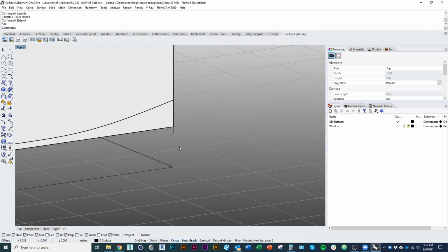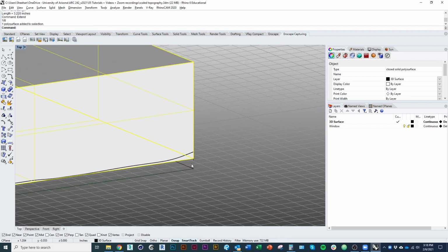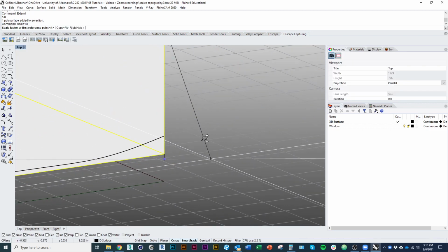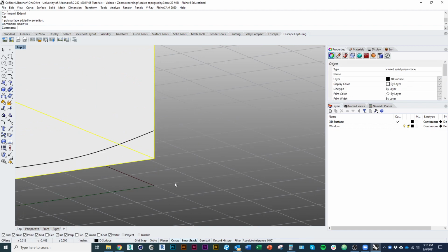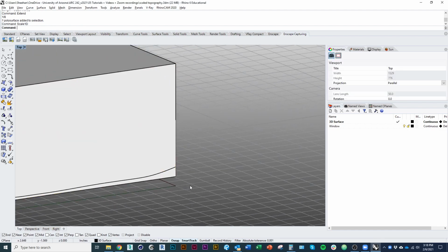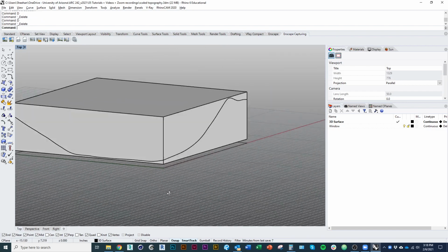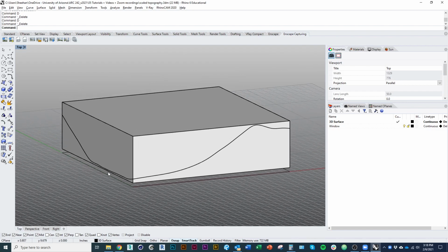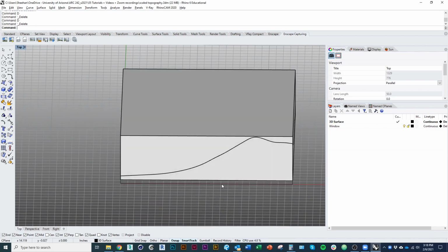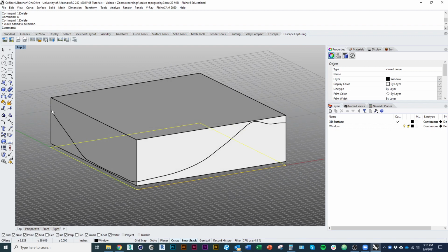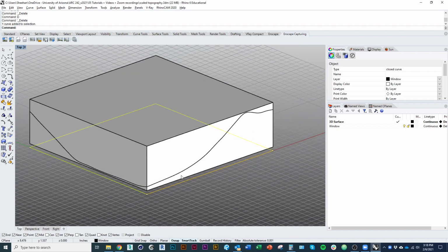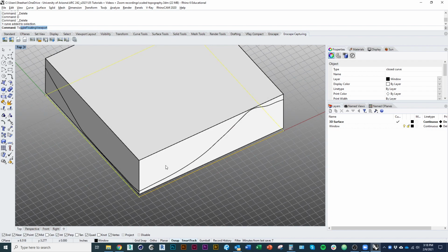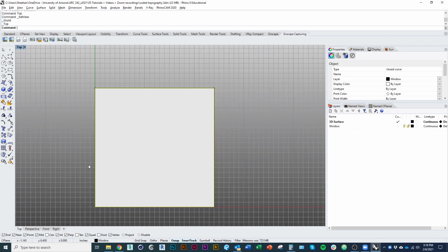And so now that line is 1/8 of an inch below, and I can scale my bounding box to that. Scale 1D, go from the midpoint of the box to the bottom, and then snap to that line I just extended. Easy enough. Okay. So now I have a box that's going all the way around my model. Again, because I used this window when I originally trimmed my topo surface, I know that that box is going to be a square in top view or in the XY plane.